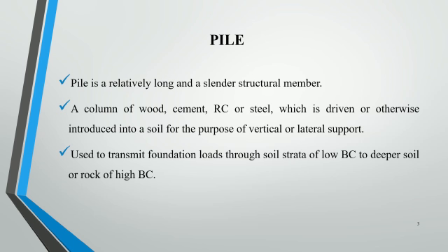First of all, what is a pile? Pile is a relatively long and slender structural member. It is made up of wood, cement, RC or steel, which is driven or otherwise introduced into soil for the purpose of vertical or lateral support. It is used to transmit foundation loads through soil strata of low bearing capacity to deeper soil or rock of high bearing capacity.